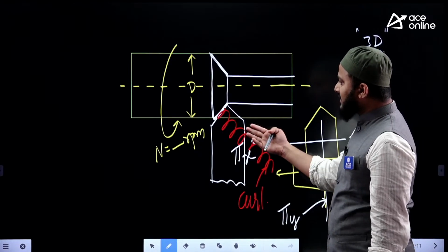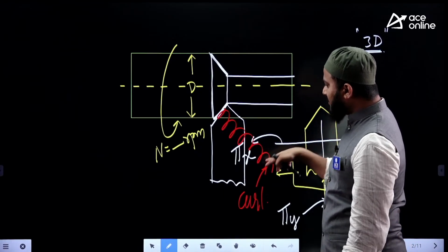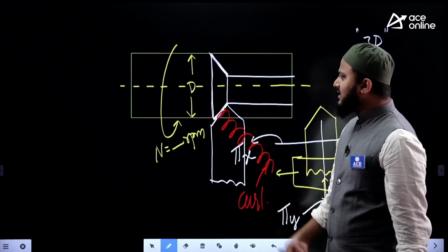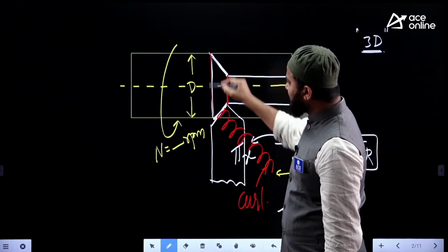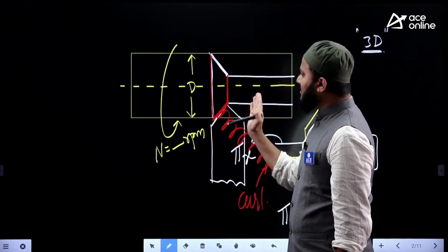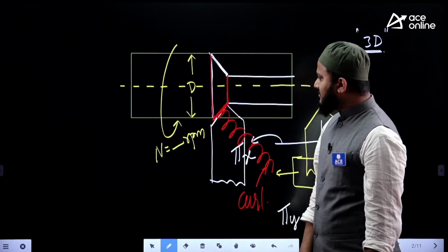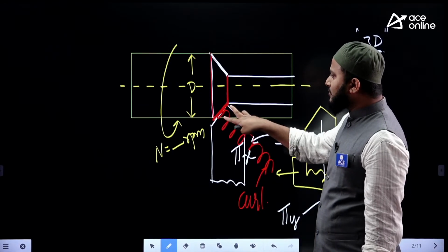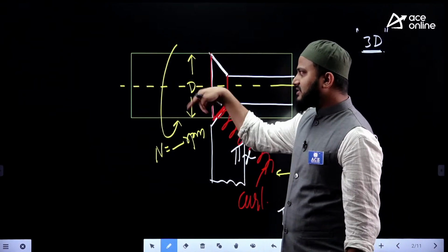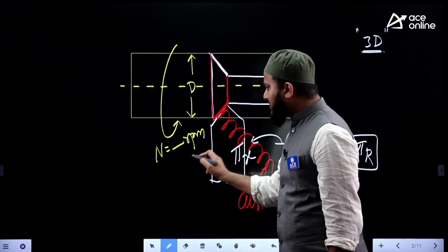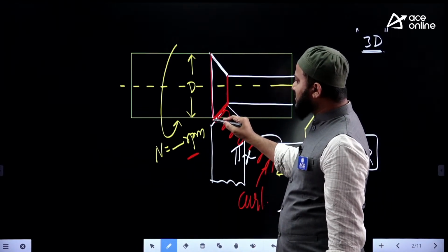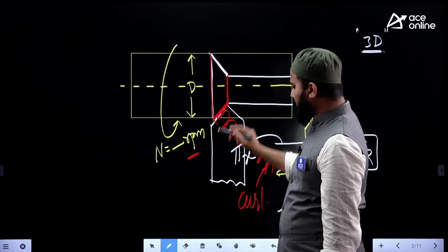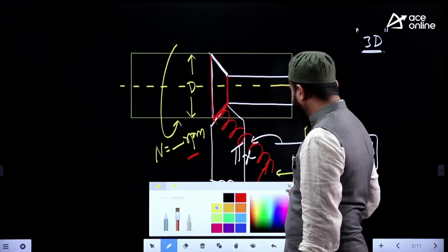So in the three-dimensional machining analysis, variable velocity causes you to get the curl. The reason for getting variable velocity is that the diameter inside is smaller and outside is larger. So the chip which is coming out over the width direction of the cutting edge has two different velocities. The rotational speed might be n, which is fixed, but the diameter difference will change the velocities of the chip. So the chip outside will come faster and the inside of the chip will come at a much slower rate.